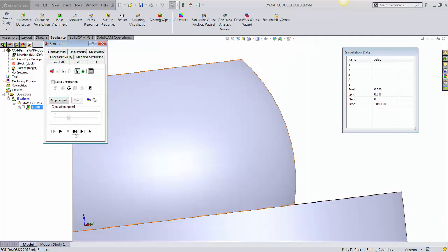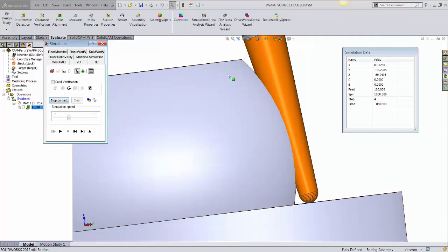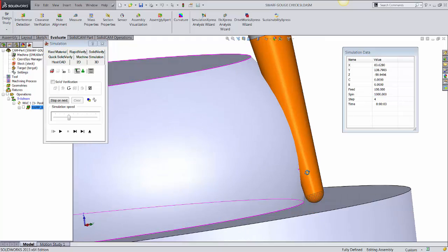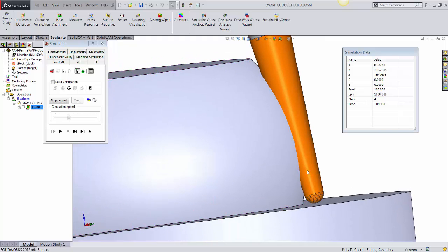Okay, this is done. Now what you're going to see here is it's still going to gouge, but the material remaining will not exceed more than 5 millimeters. So it tries to create a balance. It will either go towards the excess material remaining, or it will try to control the gouge. If it's unable to balance between these two areas, then it will try to go to the nearest possible solution of either keeping less excess material or gouging less. So the nearest solution for it at the moment is that it's going to have very little excess material.